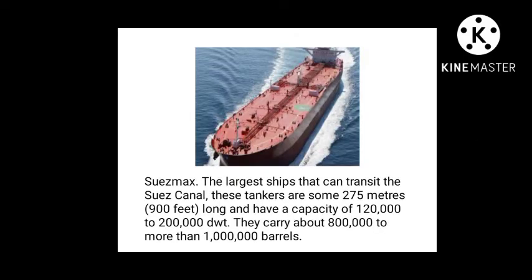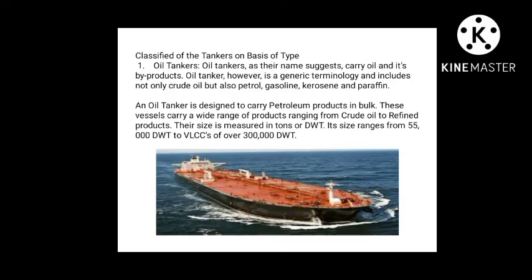And Suezmax. Suezmax is the largest ship that can transit the Suez Canal. These tankers are some 275 meters or 900 feet long and have a capacity of 100,000 to 200,000 deadweight tons, and they can carry about 800,000 to more than 1 million barrels.